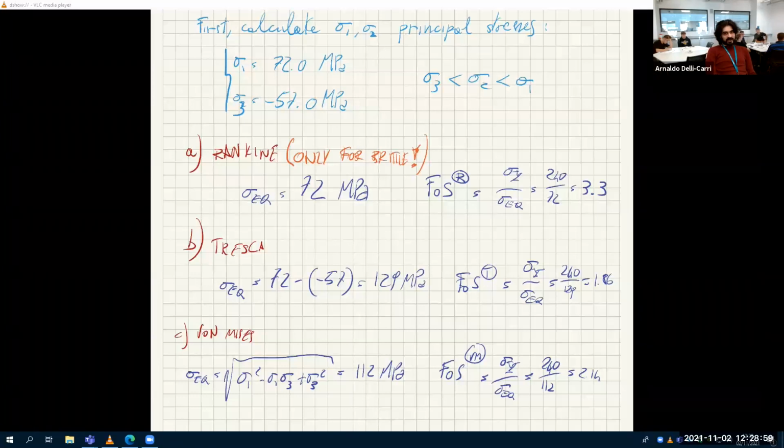It's complicated, okay? It's complicated because I'm sure it's not just the designer's responsibility in that case. It's most certainly the company's responsibility that must have used the correct one. Also, it's very, very narrow. It almost never happens that you are in this range for which one is safe and one is not. But generally, if one is safe and one is not, you always go on the conservative side and say, okay, let's make the Tresca criterion safe. Okay, second?